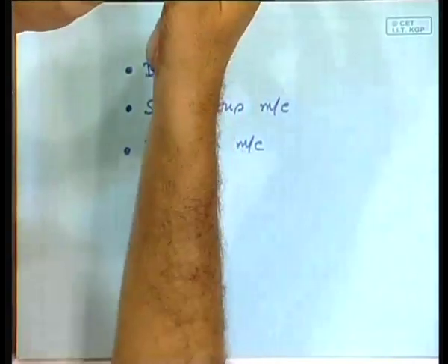So, you have to have brushes and carbon contacts. These are somewhat cumbersome, and prone to difficulties. There is flashing, sparking in the brushes, they have to be replaced, there is a maintenance requirement. Due to all this, unless you specifically require a DC machine, nobody uses a DC machine.